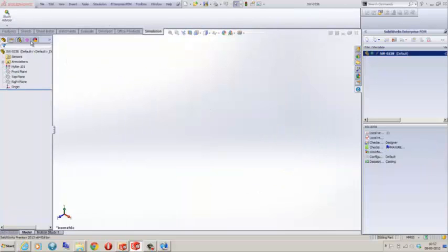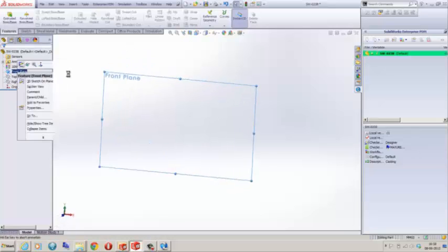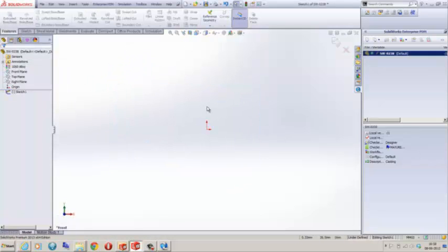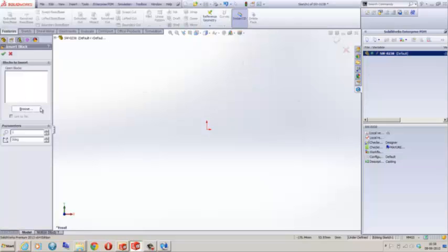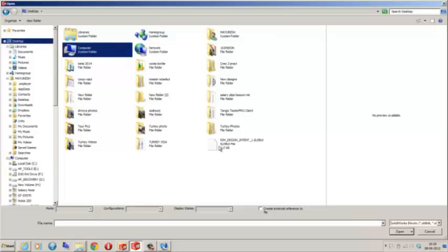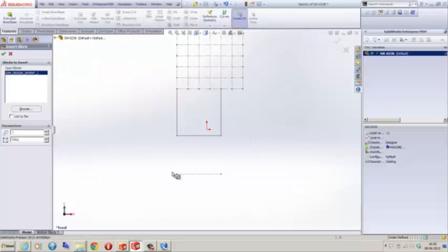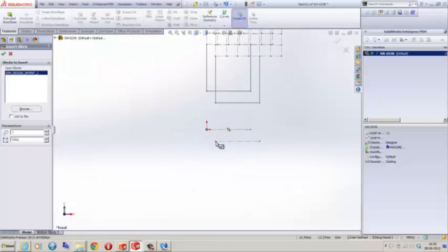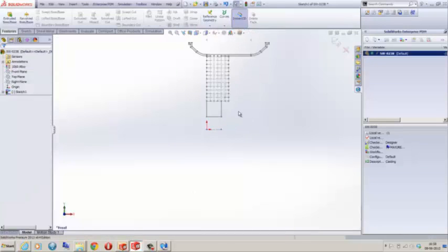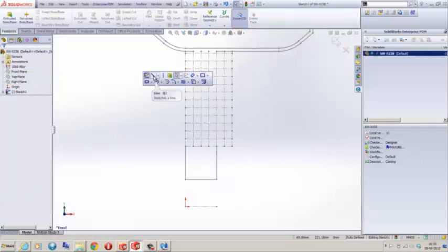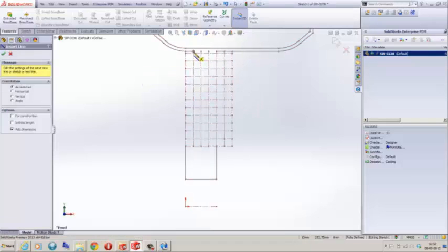So you'll be going to the new document. Here I'll be creating the wheel part. Let's start with creating some sketches. I have a block which is already created, a standardized block that I already have with me. I can open the block and paste it on this particular sketch plane. There is a manufacturing or designing area specified earlier itself, so I don't need to get out of this grid that I have here.